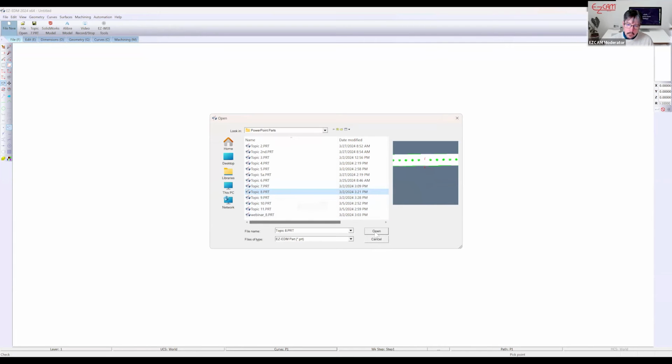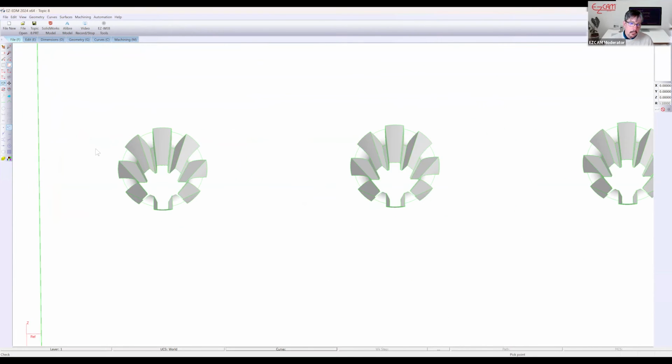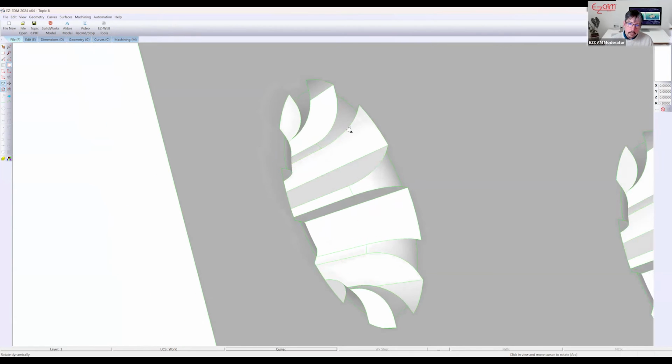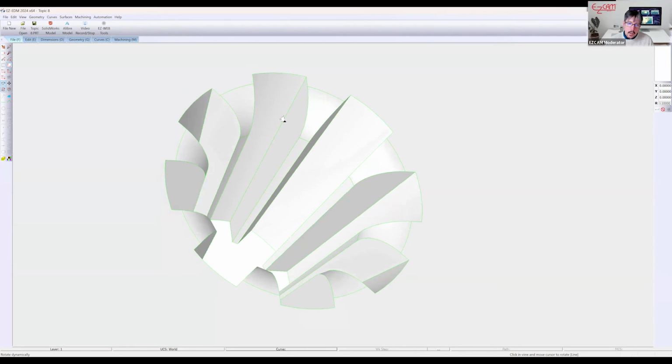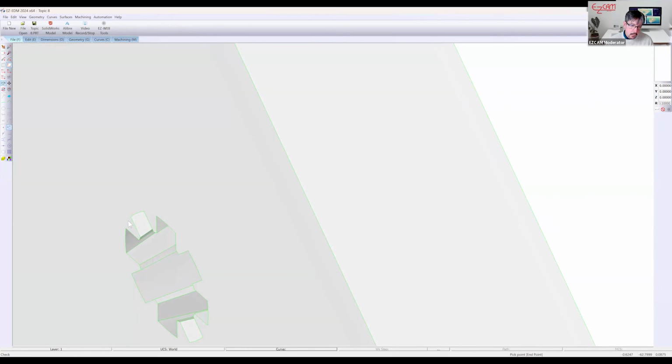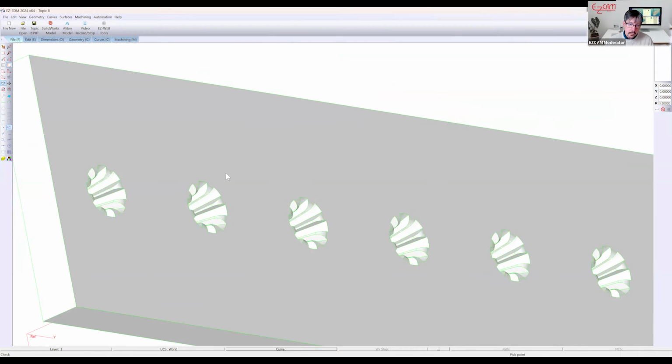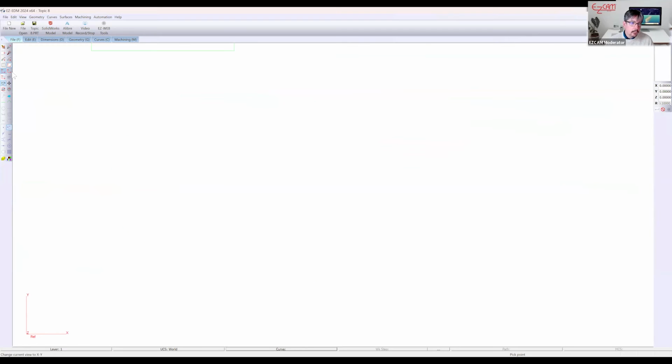All right, now we're moving into some 3D work. So that curve's a little more complicated. And this is just a straight base on that. So let's do a top view. Click once on the magnifying glass and click once on the screen, and EZ-CAM zooms the model into full screen. I'm just going to rotate that. I like to be left to right. So we'll move it 90 degrees. XYZ 0.